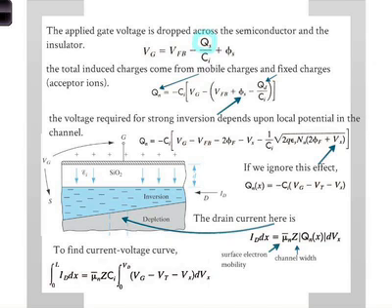I thought that the negative charge would attract the holes and have it tilting the other way. So the negative on that side would attract more holes, and I would expect the inversion to be thicker on that side. No, the inversion is primarily controlled by the gate. But the tilt of it, doesn't that depend on which?